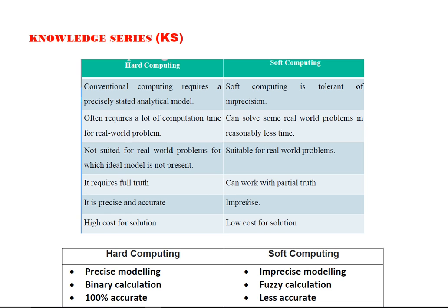Whereas in this case you need linguistic variables like low temperature, medium temperature, high temperature, and based on those linguistic variables we can take values ranging from 0 to 1, and thereby we can give a command and create an inference. Inference is nothing but a range between low and medium, or medium and high, and thereby we are able to control it.